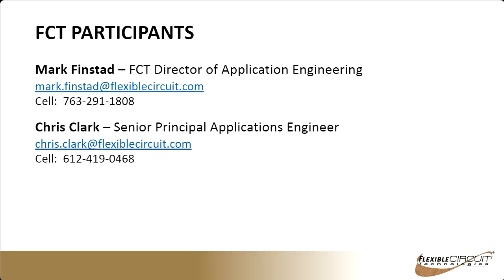No, that's probably it. There's another question just came in. What are the disadvantages of directly soldered wire leads? Actually, there's no disadvantages. We do that on a pretty regular basis. The only drawback to leaving them open is if you have other metal objects that might come in contact, you could have a short. That's the only reason we pot them, but we solder wires onto virtually all of our heaters. That's the most common way of making the connections.